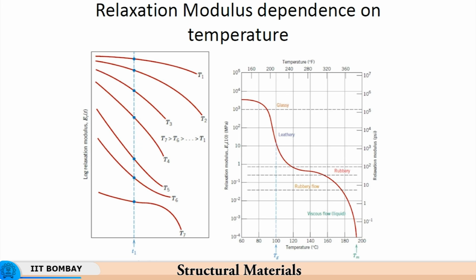So these are shear thinning materials. If the shear rate during flow increases, then the viscosity decreases. That is what we call a shear thinning material. These polymeric chains present in the molten liquid impart the property of shear thinning to it.